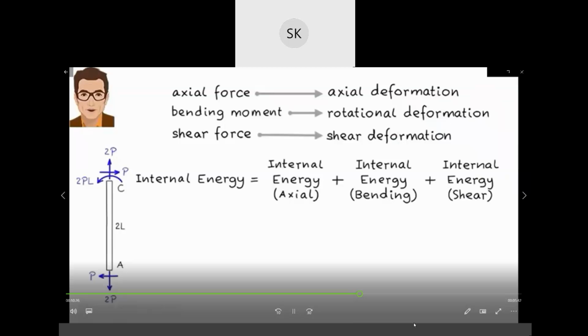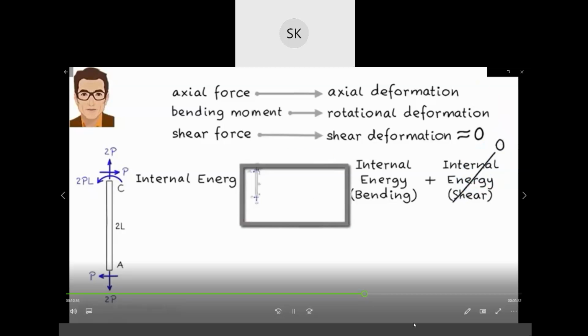However, shear deformation in beams is generally negligible. Therefore, let's omit the last term. For the axial case, we basically repeat what we did for member BD.